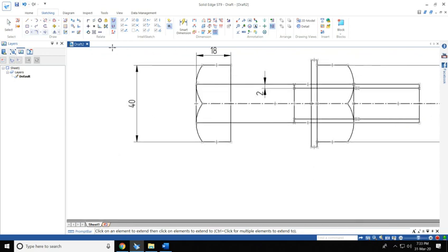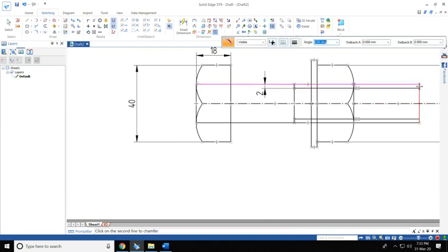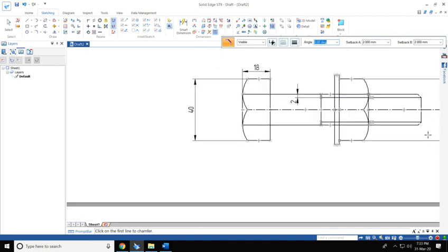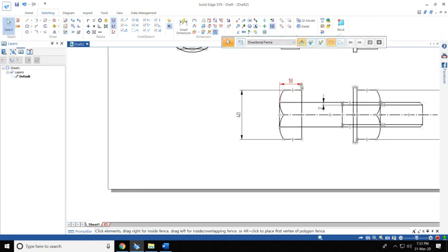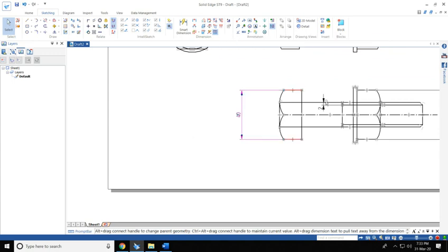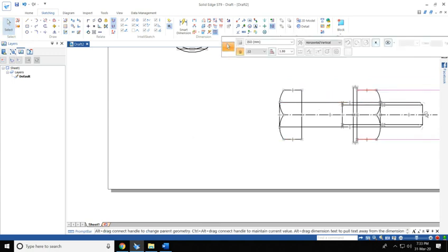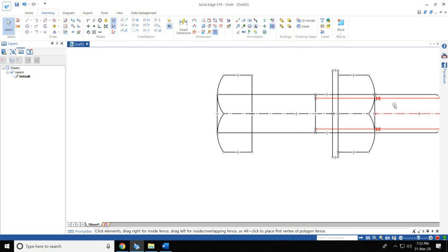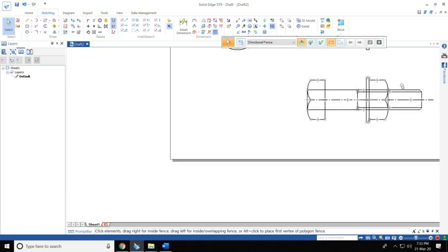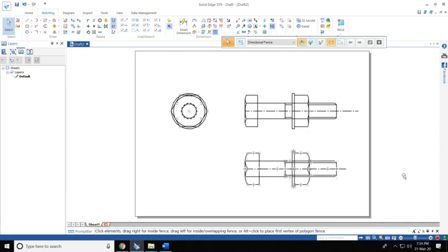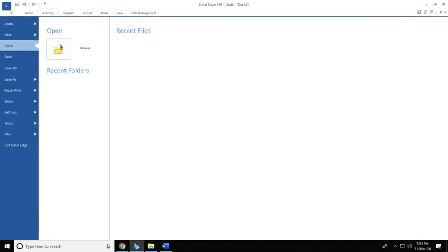Done. And the one last thing remaining is the chamfer. We'll take chamfer, these two, set back 2 mm, set back 2 mm. Done. And these two, by default it will be 2 mm. And then now you can remove your dimensions and these extra points, which are not necessary. Like when you complete it, you'll have to show it in JPEG, so we'll save as